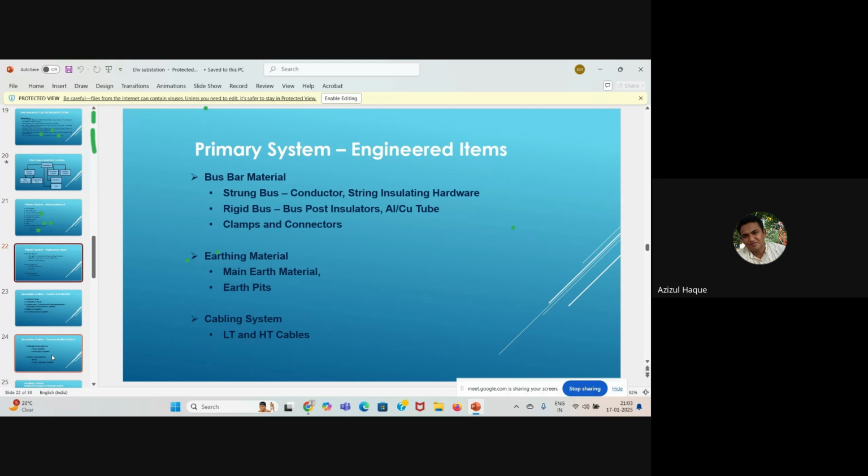The earlier connector maybe can be used if both terminals are the same, but not necessarily always. It cannot be used if the terminal pads of the ABB breaker are different from those of the Siemens breaker. So if I want to replace that breaker, at the same time I have to check my connector type, whether I have to change it or not.